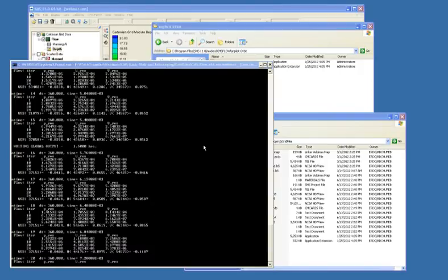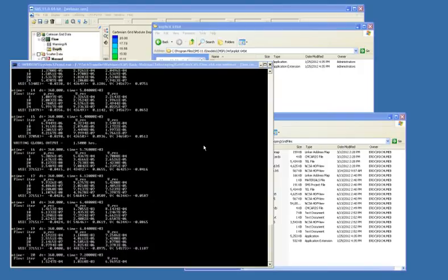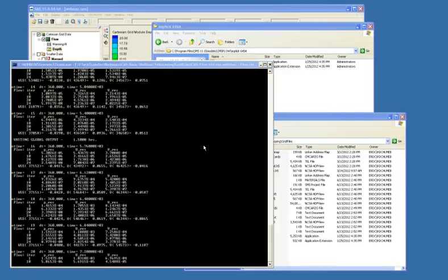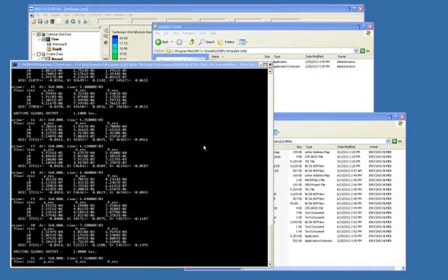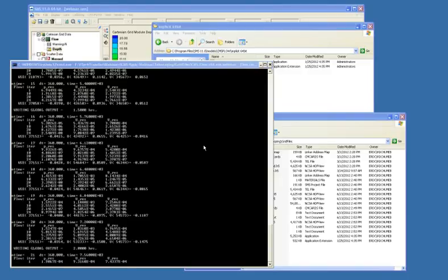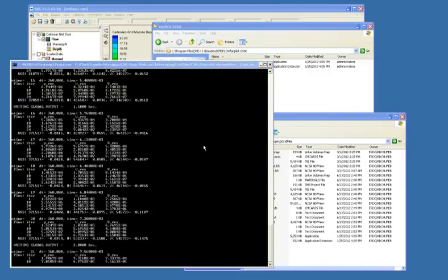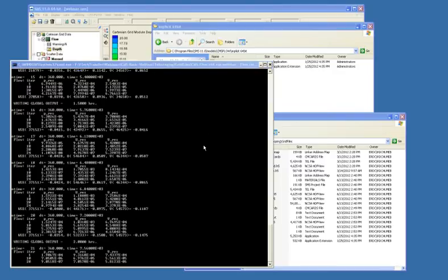Now you can run a combination of AdCirc and CMS Flow and get an AdCirc-based water surface elevation to force a smaller CMS Flow grid. We've done that in the past, but that's primarily the differences between AdCirc and CMS Flow, other than AdCirc is a finite element model using triangles, and CMS Flow is a finite volume method using rectangles.